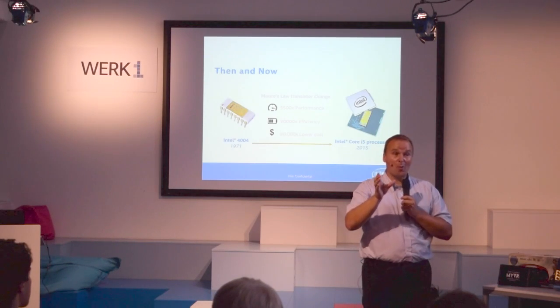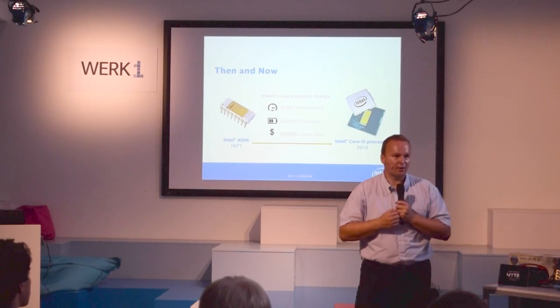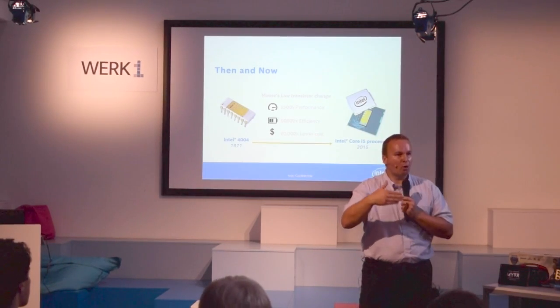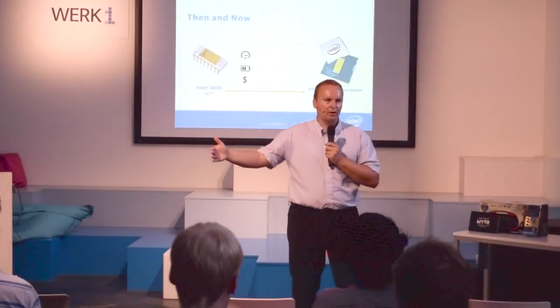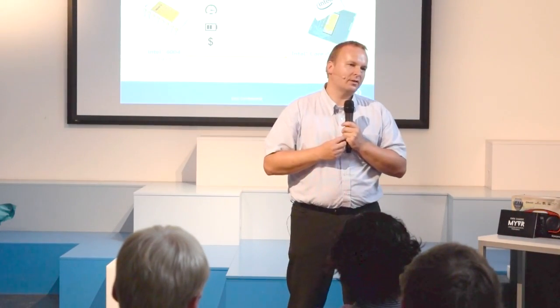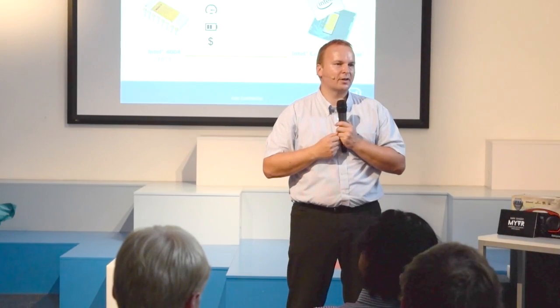And we're also using wet masks now, which also helps the lithography. So it's getting more complicated. The throughput time in the factory is getting longer, which causes a whole lot of problems for us in order to produce the amount of processors that we want. But these are all workarounds in lack of having a source of light that is much smaller in wavelength than the 193.